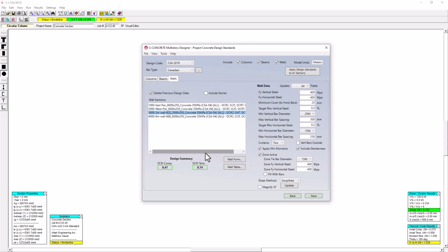We're performing an initial high-level check, in this case here for walls. It's doing this just for the axial check. So this has utilization ratios. Let's say DCRC equals 0.25, so that's the demand capacity ratio for compression is 0.25, and for tension it happens to be 0 for this case. And so we can actually get an understanding of the high-level performance of our model for axial checks at this stage already.